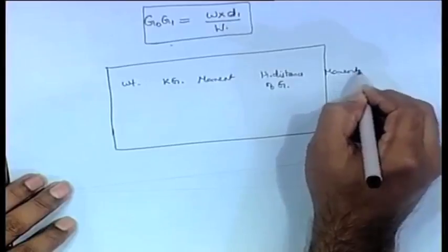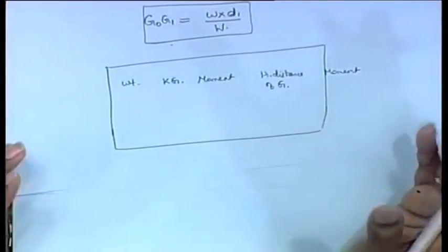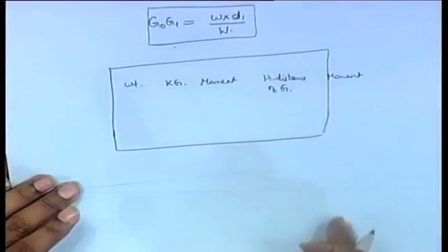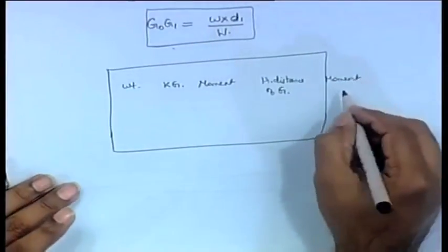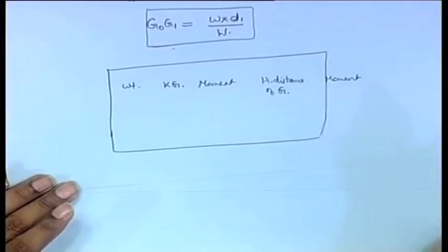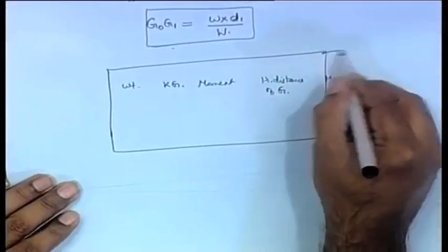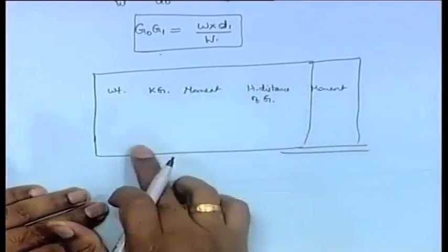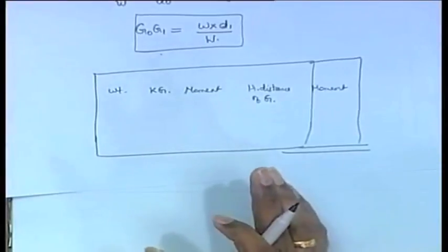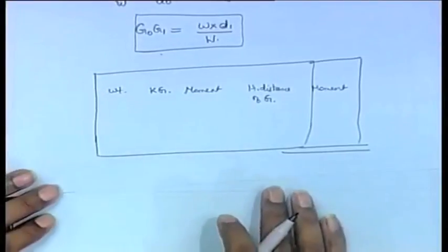You can put the port moments as positive and the starboard moments as negative, or you can put different moments, but a concise way of doing it is port moments as positive and starboard moments as negative, and in one table like this you make the whole thing. This moment divided by the total weight gives the answer. It is basically the same problem, just written in a different fashion.